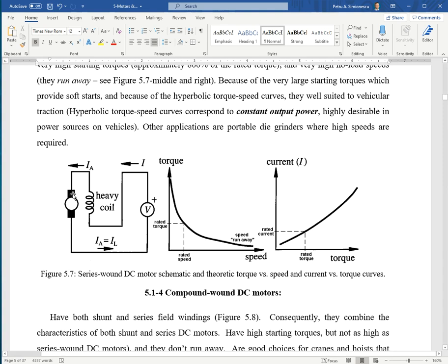So if I have an engine starter motor rated for 24 volts, you can power it at 12 volts, but you'd expect to have half, if not less than half, of the maximum torque.